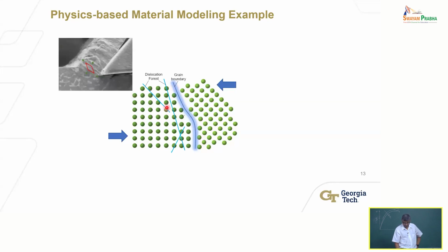And what's happening? There are dislocations in this material, defects that are there, right? Edge dislocations would be a missing half plane of atoms, right? And when you deform the material, these dislocations will move, and new ones may be generated, and they will interact with each other. And you need more and more force to cause them to move past each other to accommodate more deformation, etc. That's what's happening.